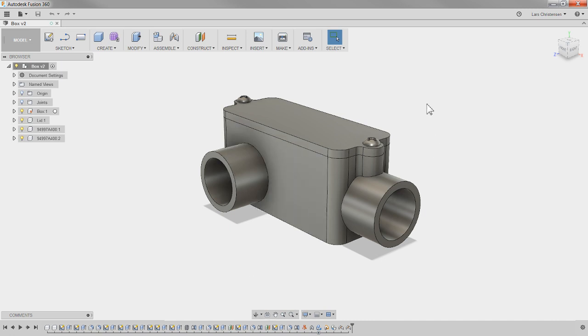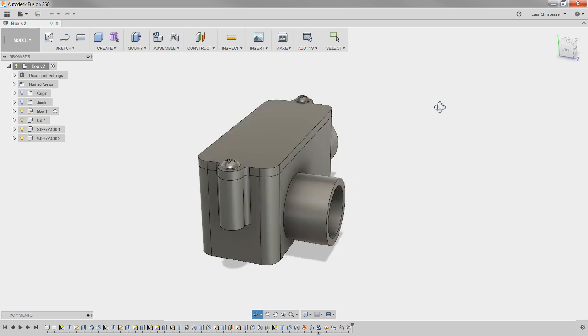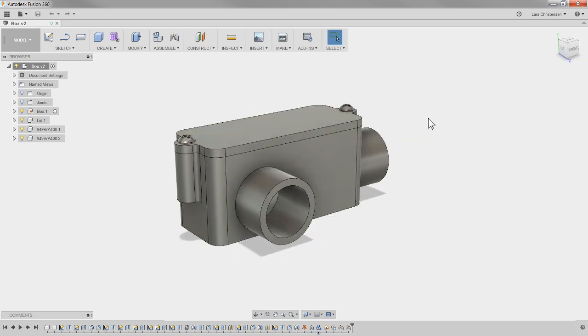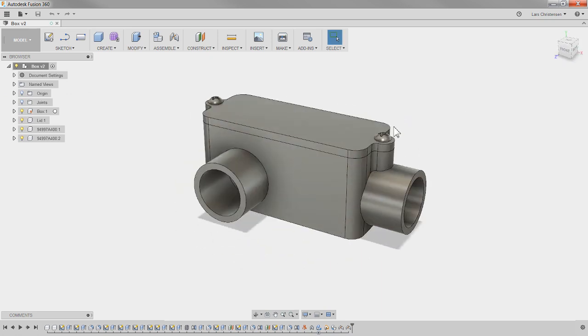Constraint Orbit. Right now there's nothing highlighted on that command down there, but as soon as I start rotating, you will see that it turns blue. You see that? Look down at the bottom of the screen on the orbit. Okay? That means that right now I am in Constraint Orbit. If I click on the little button here, there's actually also a free orbit.